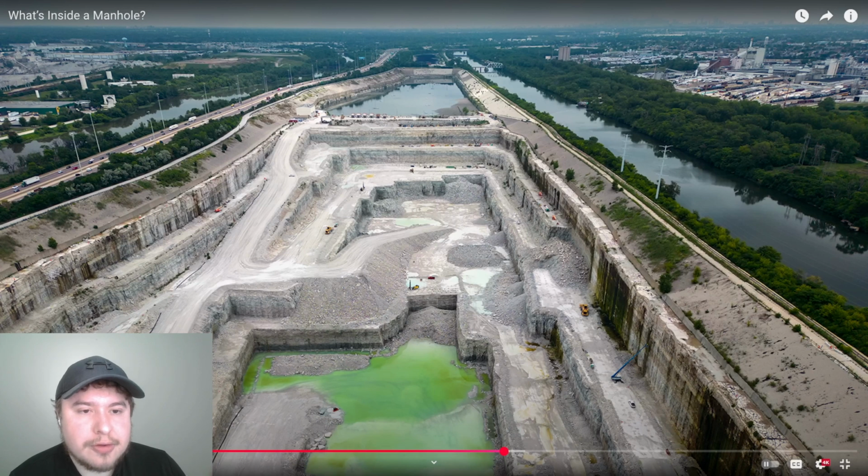So basically, those manhole segments, those larger cylinders, add a buffer, so to speak. That way, the actual piping and the angles, I believe, is what determines the throughput of the pipes. And so that will stay static throughout the day and throughout various events. But by having those cylinders, it allows you to accumulate excess for some short period of time. And presumably, if your system is set up such that it is over capacity for standard load, then when these severe scenarios are done, you start to remove some of that excess over time naturally.